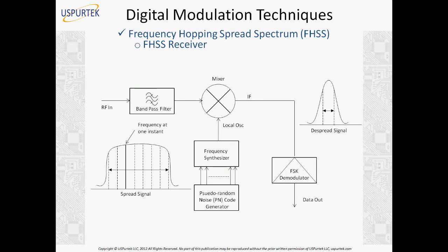But here, in the case of FHSS, we are hopping from one frequency to another, suddenly changing frequency in the oscillator, like now it is 1 megahertz, next time it is 5 megahertz. So switching from one frequency to another, we do not maintain phase. The next frequency we choose may be starting from a different phase angle.